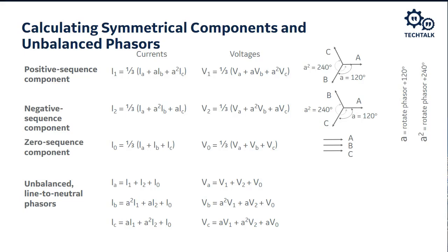If it's going to be exceeded, I might not be able to break the fault current that I have. This is one of the fundamental things that we should know as protection engineers, to be able to know what the fault current level is at a particular location in our power system. This will be important for all of our protection, not just the relays, but the breakers as well, because we don't want to overduty those breakers.